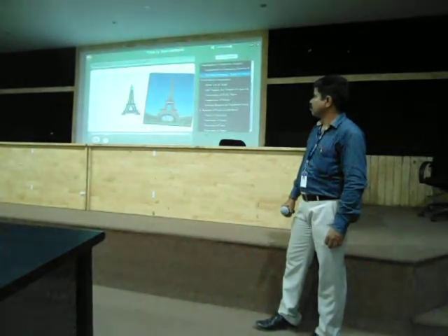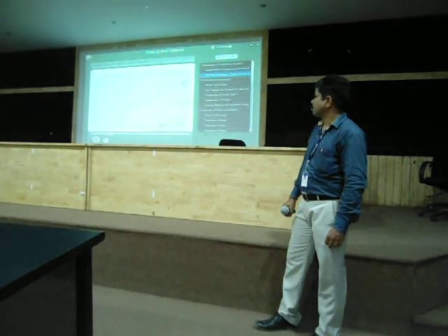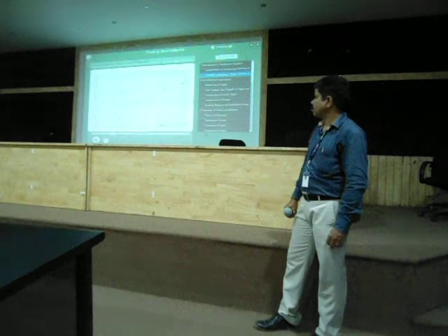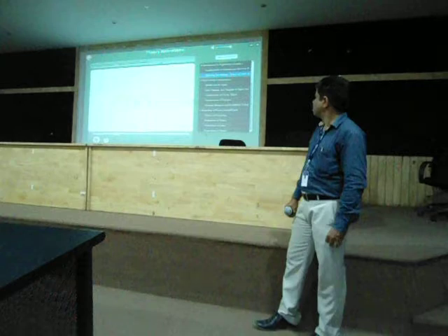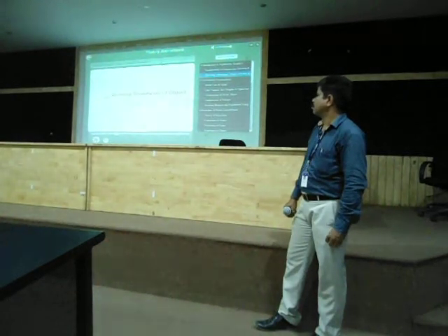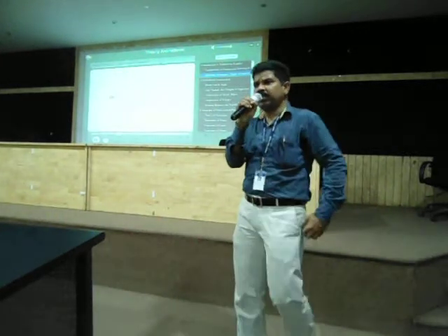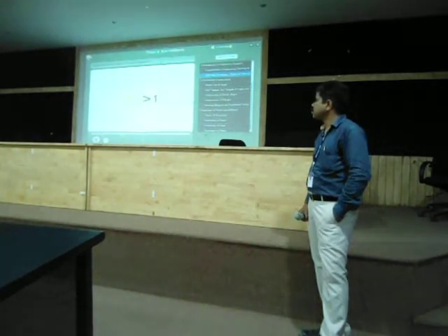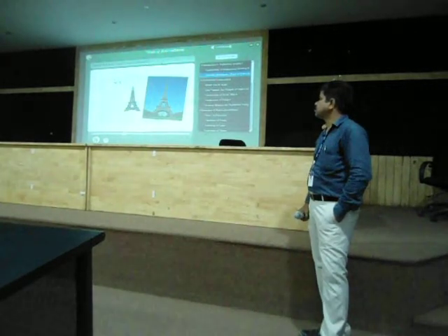However, generally the prototype is either too large, for example the Eiffel Tower, or too small, for example a micro-scale motor, and we will have to scale down or scale up the dimensions of the prototype in order to represent it on the drawing paper. The representative factor, RF, is a ratio of drawing dimension to the actual dimension. If RF is greater than 1, then the drawing is enlarged. And if it is less than 1, then the drawing is a reduced view of the same object.